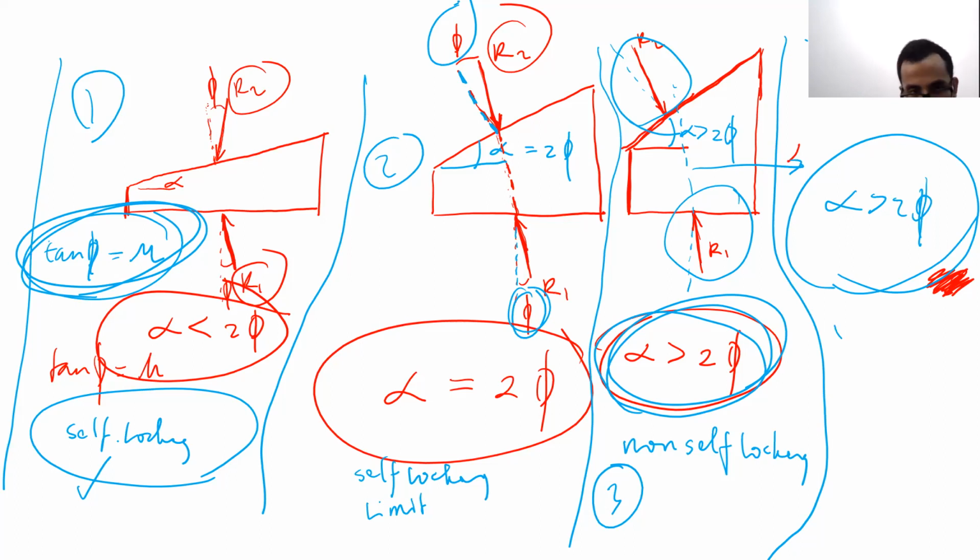Oh, okay, understand, sir. Yes, sir, R1 is actually the summation of the normal force and the maximum friction force. Maximum friction force is based on the mu s. So basically the real free body diagram will not be the same as this one. It will stay in equilibrium, but the friction force will not be the maximum friction force. It will depend on the condition. It will react to what is happening there. Do you get it, Matthew?